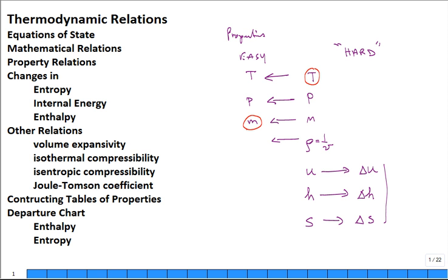Or thermocouple. How many people take M&I in other classes? You've seen a thermocouple? How does that work? You measure something and infer temperature. You measure little millivolts because dissimilar metals, 2 types of wires put together on one end, on the other end, they connect, they make a loop. And if their junctions are at different temperatures, you have a little millivolt type of potential that would drive current. So that's how thermocouples work. So often, we don't measure temperature directly, we measure it indirectly through some relationship.